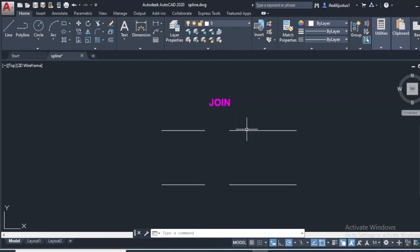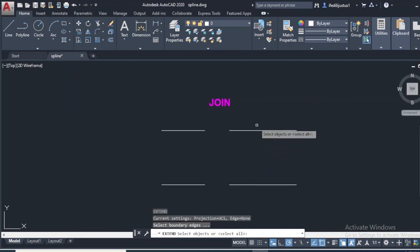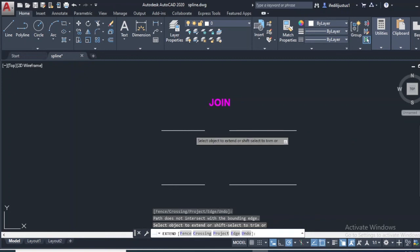The main thing here is I want to actually join this line with this one. If you want to use the extend command, type in extend, enter, you see that it is not actually possible to extend them because they are on the same plane, they are concurrent. So extend will not work on this one.